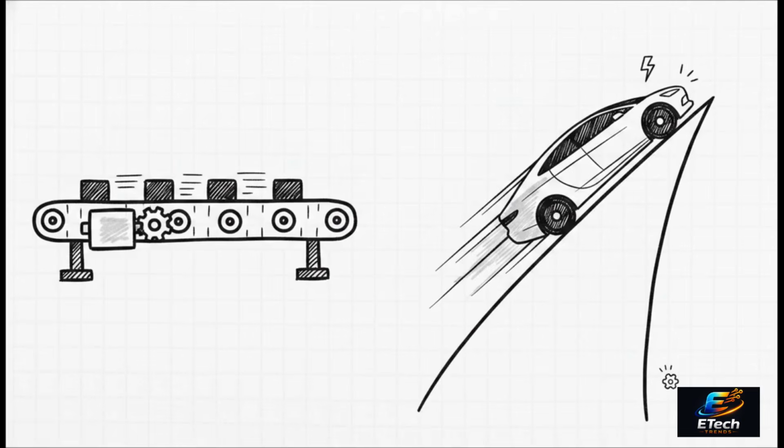And the crucial takeaway from the resulting data? Well, while open loop works totally fine for fixed-speed industrial tasks, the closed-loop system is mathematically proven to be significantly more precise for the dynamic, unpredictable environment of an electric vehicle. By using PID controllers, the closed-loop system dramatically reduces steady-state error, mitigates error sensibility, and delivers a highly smooth, high-performance speed response, even when the vehicle suddenly slams into that 20-degree incline.